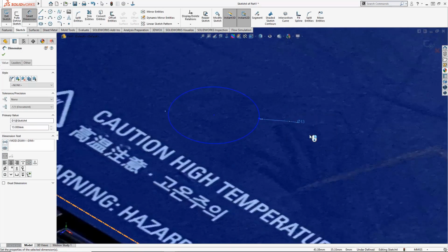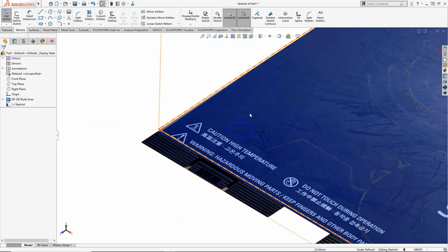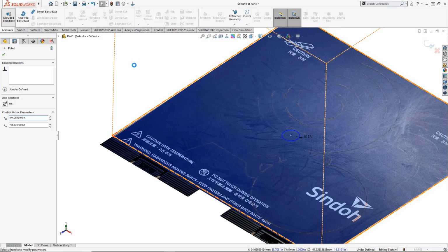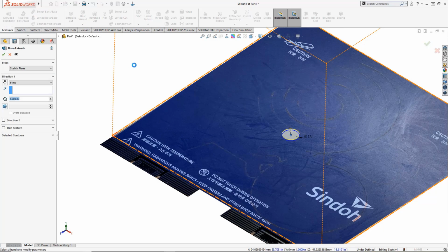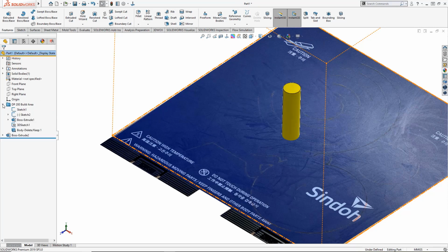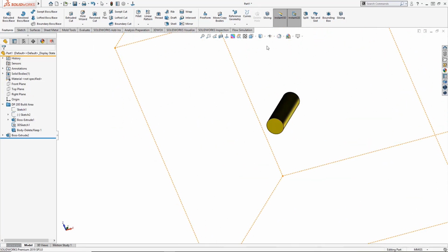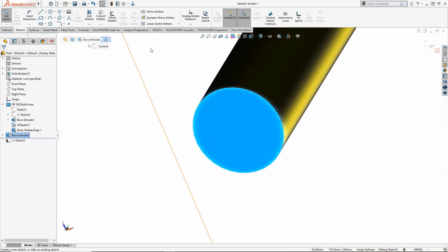Now for starters, I'm going to go ahead and model up the rocket motor. It's only 13 millimeters in diameter, and really just for sake here, I don't necessarily always work with underdefined sketches, but I'm just going to put it in the middle of my build tray just for safekeeping. We'll go ahead and extrude this 44.5, and then from there, we're going to go ahead and just clean up our display a little bit. I don't always like to see these, but I am going to go ahead and leave the bounding box because that'll let me know whether I'm violating a particular volume.